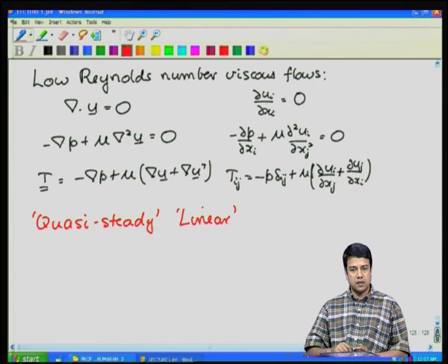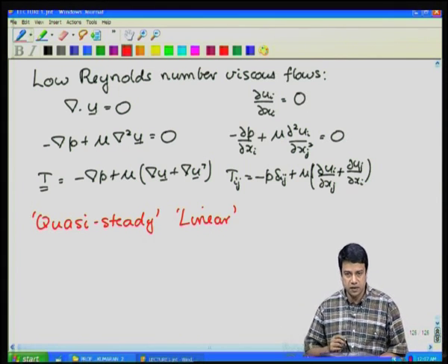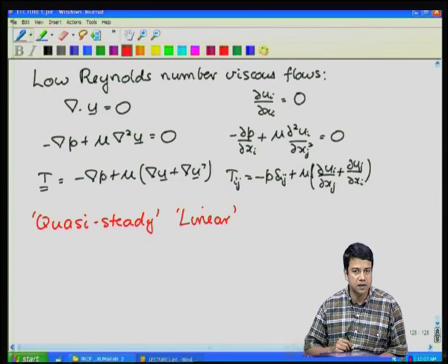The flow in the limit of very low Reynolds number is reversible. That means that if I reverse the direction of either the velocity or the stress on all boundaries, then the velocity at each point in the fluid exactly reverses. If I double the velocity or the stress on all the boundaries, the velocity and pressure at each point within the fluid increases by a factor of 2. Okay. Because of this combination of linearity and reversibility, we had discussed many interesting consequences in the previous lecture.